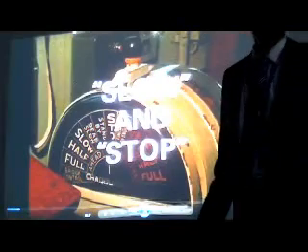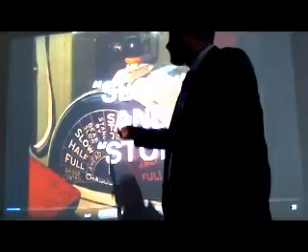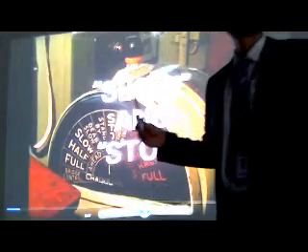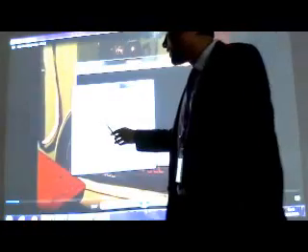And for the general conventional method of communication as well, the way we have trained people at sea, nobody is going to say make RPM 10, make RPM 20 or make RPM 30. There is a set way of saying things. As you can see, it is mentioned here, one is stop. Stop is 0. Even in the stop position, if it is a CPP ship, stop means the pitch is going to be 0.